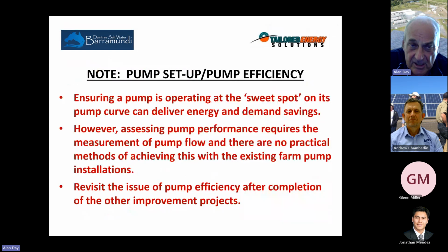I just wanted to mention pump setup and pump efficiency. It's not that we're ignoring it. It's just that in our experience, pretty much everywhere we go has not got pressure gauges on their pump systems. They certainly don't have flow meters. They don't have lengths of pipe that are accessible, clean lengths of pipe where you can strap on an ultrasonic flow meter.